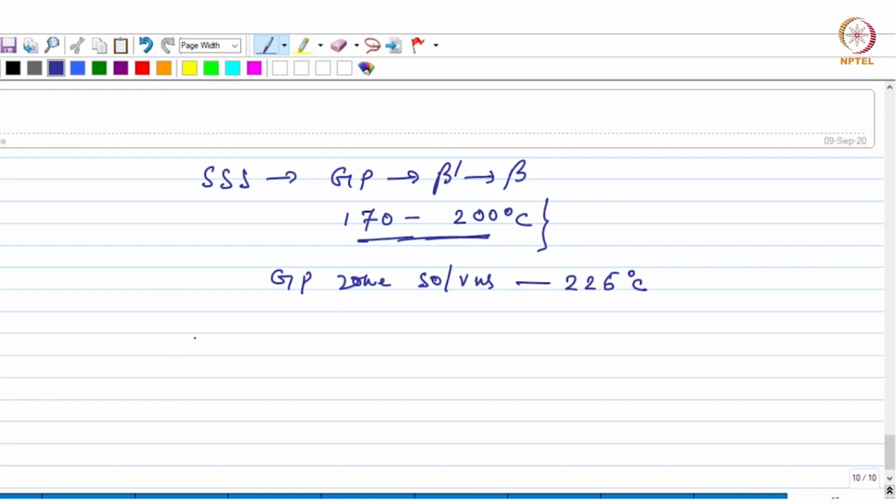And this precipitate will form for a particular ratio between magnesium and silicon, which is around 1.73:1. In some cases there may be a little excess silicon, and that will in fact give rise to higher strength but lower corrosion resistance.